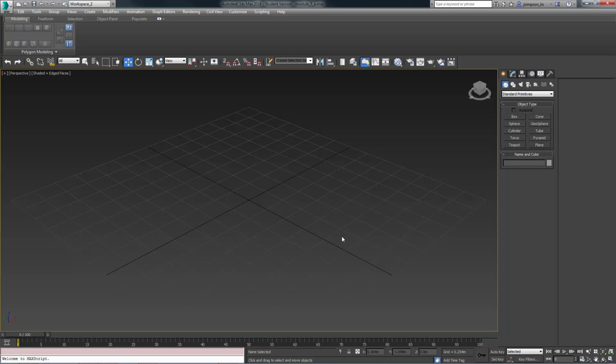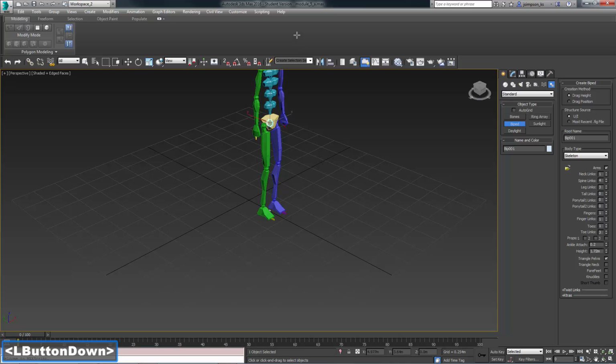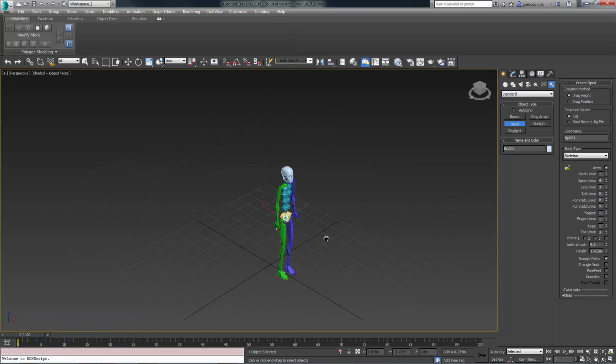To further help with scale, I will be using a biped object. A biped is used for rigging a model in Max. Rigging is the process for creating a control structure for a model, similar to what we did with the dummies and the chess pieces. A biped is found in the Create Systems panel. We will be using it as a reference object to help us manage scale. An average North American male is around 1.75 meters tall.